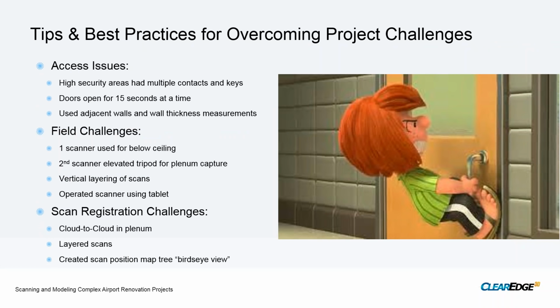And Daniel indicated this as well. All of us in this industry deal with access issues in buildings, and sometimes this is the number one job killer for most projects. In this and other airport projects that we've done, the locked door access might be TSA, it might be another authority, or a private tenant in the airport. Despite their best efforts, we ran into a lot of locked doors and had to have multiple contacts, multiple people. We even ran into some high secure areas where the door could only be open for a very short period of time. So they had to scan adjacent walls and measure wall thicknesses in that short period of time in order to wiggle in a scan registration inside these ancillary rooms off to the side. So that was sort of unexpected.